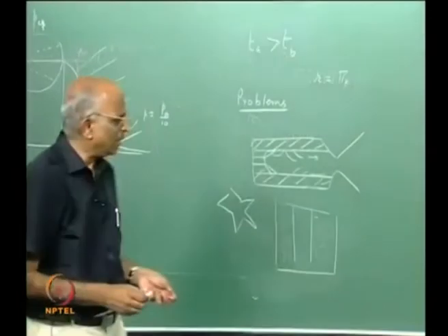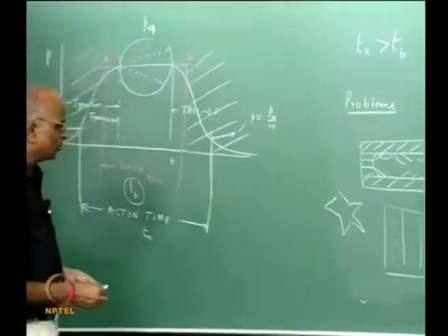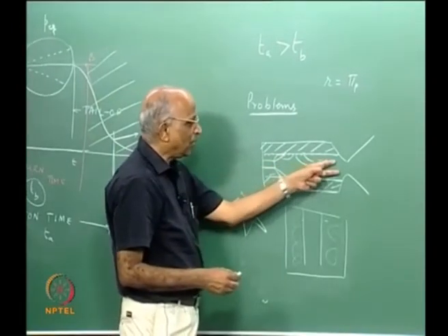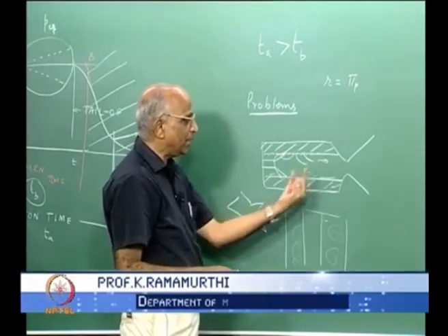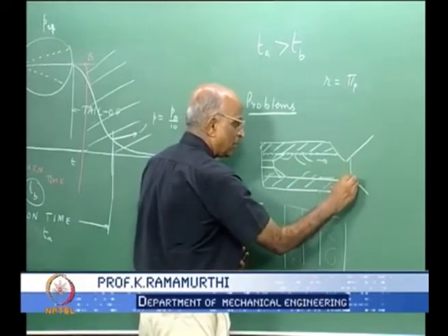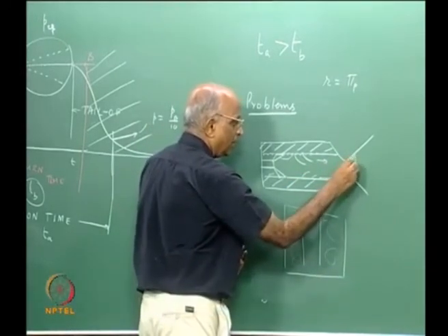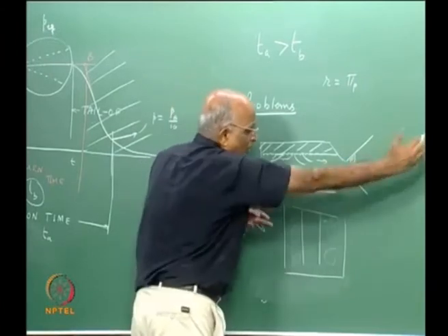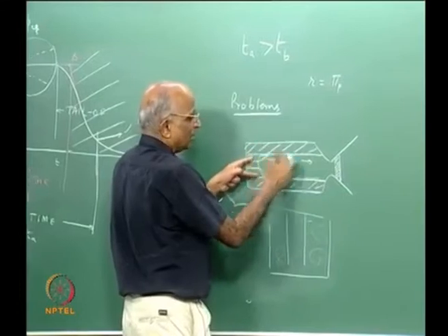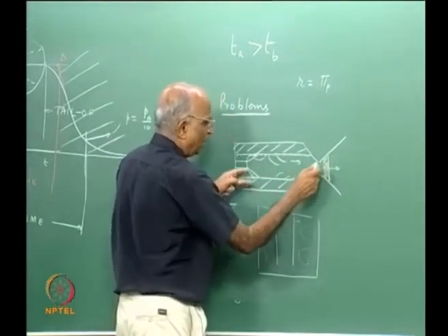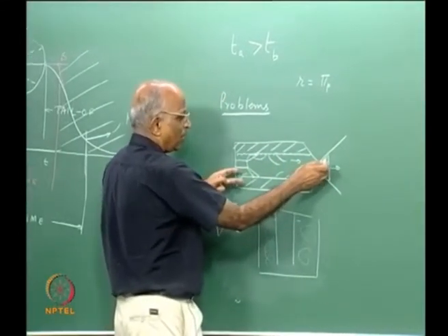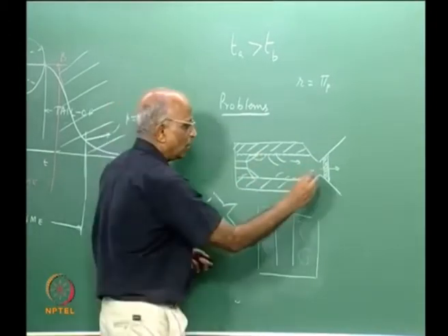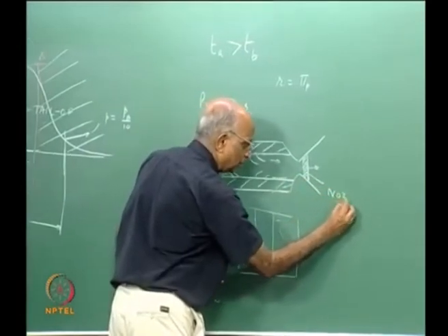Something which I missed out telling when we talked of igniters was, very often when we ignite a motor, the gases are going out and some of these motors have to ignite in vacuum, and therefore we put something like a closure here. We initially close it like this, and when pressure builds up this goes off, and once the motor is ignited this gets thrown out. Let us make sure that this is around 5 bar to 6 bar such that some minimal pressure gets created. This is known as a nozzle closure.